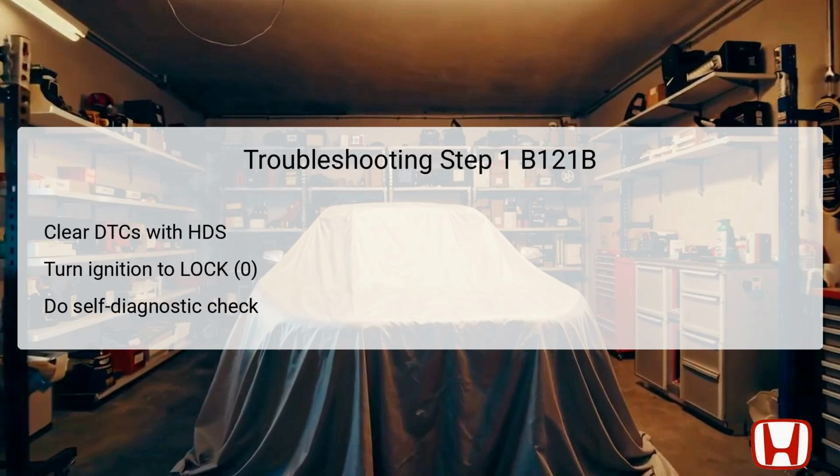The first step in troubleshooting DTC B121B involves clearing any stored trouble codes using the Honda Diagnostic System, or HDS. This procedure ensures that no previous fault codes interfere with the current diagnostic process. After clearing, turn the ignition switch to the lock position and then back to the on position to reset the vehicle's systems.